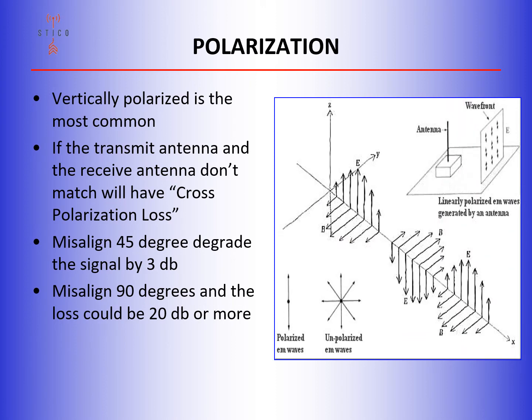Polarization of an antenna is how the waves radiate away from the source. Whether by design or physical orientation, just note that the polarization of your receiver system should match that of the transmission system. In other words, if your mobile antenna is vertically polarized, the receiver system that you're operating into should also be vertically polarized. If you use two different types of systems, for example, horizontal and vertical, you will begin to incur loss. Note some of the misalignment degradation that you're going to see in the following slide.